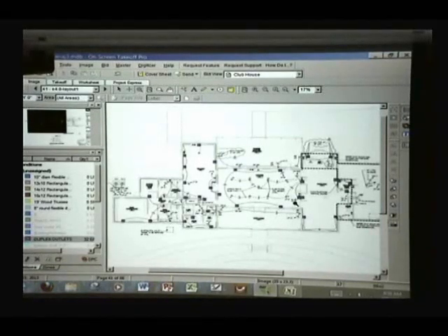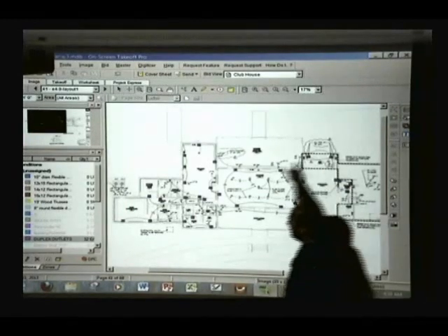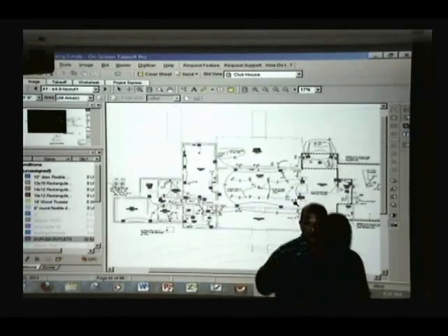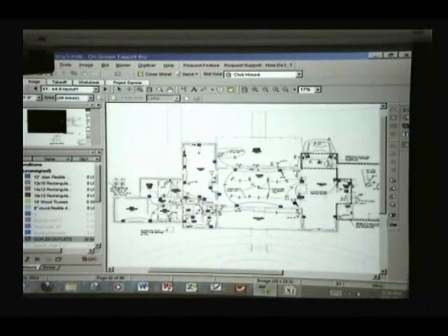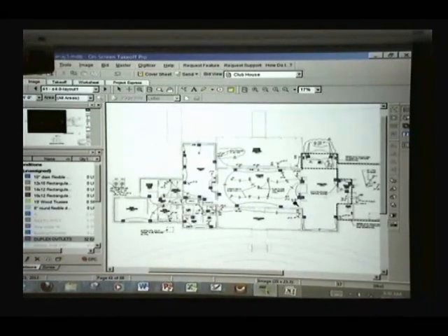Send that information over to your spreadsheet and then look it up. Yeah, that's right. That's one way. Another thing that we need to do is to estimate the area, right? So we can estimate how many outlets we have per 1,000 square feet and use the correct table in RS Means, right? So I'm going to do that.